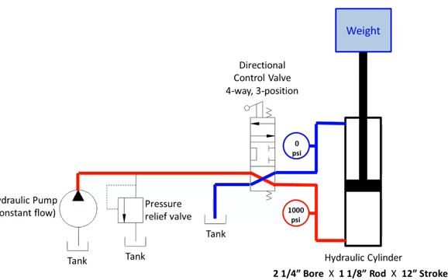Let's say the pressure was able to build to 1,000 psi. If you remember from your high school physics class, pressure acts in all different directions. So there would be 1,000 psi of pressure in all different directions in the bottom of this cylinder. The pressure on the outside walls would try to burst the cylinder open, so we would need to make sure that the wall thickness was sufficient so that the cylinder didn't burst open. The pressure along the bottom would try to blow off the end of this cylinder, so we'd need to make sure that that was strong enough.